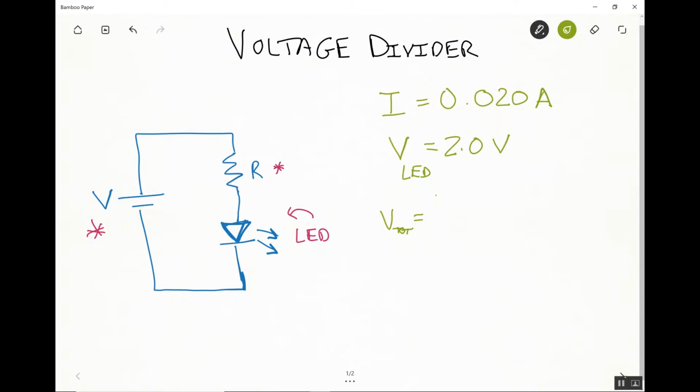Okay, here's that data sheet in another application where we can zoom in and I can mark it up. So the things that we want to pull out of the data sheet, which tell us how to design a circuit to make this green LED work, is we need to know how much current it needs. That's in the data sheet here labeled as forward current, and the units are milliamps, 20 milliamps. And we also need to know how much voltage is required.